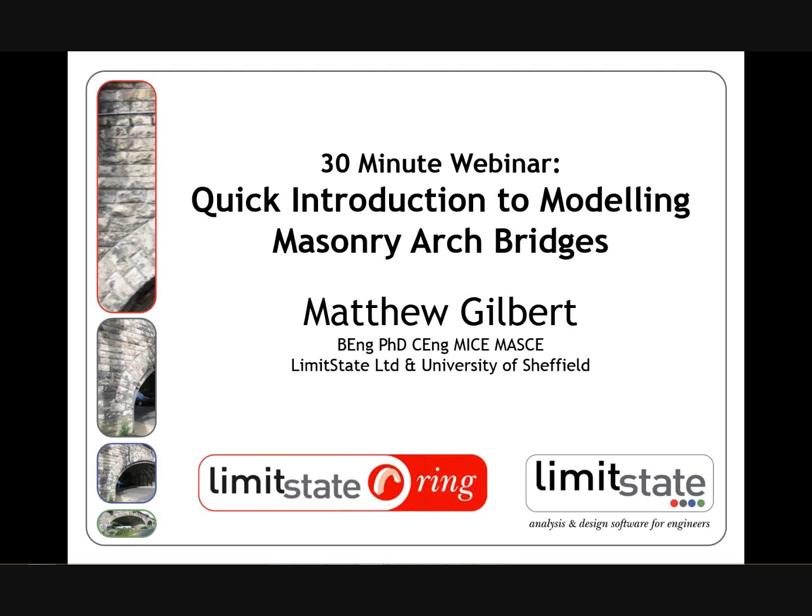I'm Matthew Gilbert, and today we'll be using LimitState Ring to highlight some of the main aspects of Masonry Arch Bridge analysis, including how to identify the critical load and critical failure mechanism, whether you're dealing with a single span bridge or a multi-span, why the soil surrounding the masonry arch barrel plays such an important role in determining the ultimate load carrying capacity, how to model the effects of both highway and railway loads, and how to quickly model the effects of localized defects and ring separation in the arch barrel.